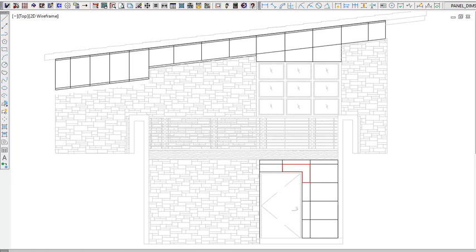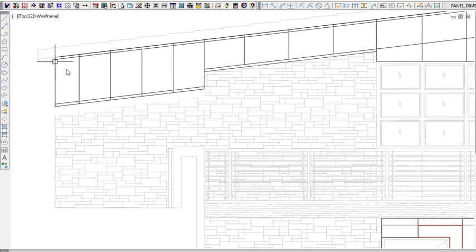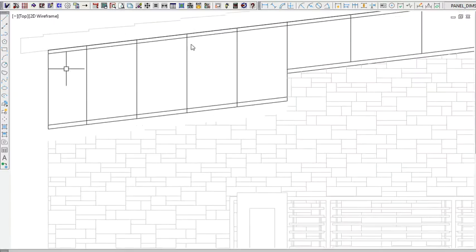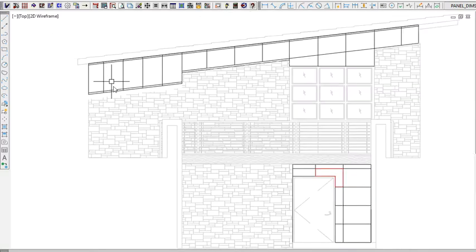And in this little episode, we're going to talk about converting an architectural background, which is a block, and converting the panel elevation panels into smart panels that the program uses. To get started, we have to notice first of all that the center line of the reveals is being used here. So we really want these elevation panels to offset what the system says, and currently it's set to 1/2 inch. So we want to take that into consideration. Let's go ahead and get started.